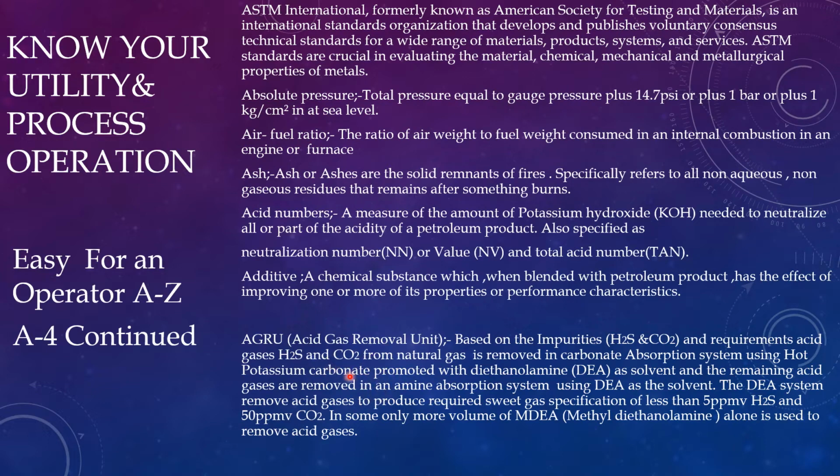and feed gas coming from the petroleum products or well will be sent to AGRU first after removing the moisture contained in some separators. So the AGRU unit will remove the H2S and CO2 from the feed gas and sweeten the sour gas. Then it will be admitted to the fractionation section. This is the main unit normally in all LNG production plants.